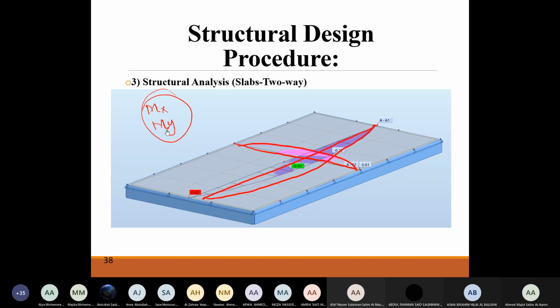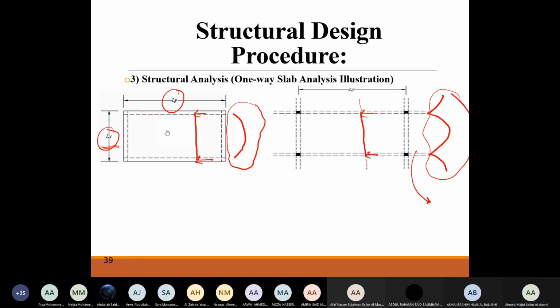Okay, to make it a bit clearer for you, take a paper and take a ruler. Paper tends to be something similar to a two-way slab, because of the dimensions. You can see that you can bend it in two directions. Try with the ruler, you will see that the ruler can be only bent in one direction. Why? Because one dimension is long, one dimension is short. I have already explained this one in the last class for you.